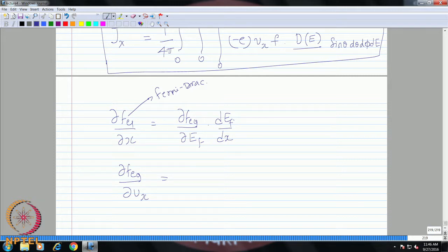Mu is your Fermi level, you can say that is your electrochemical potential mu. At 0 Kelvin, that is your Fermi level. Okay. So, that is a function of x when you have a charge gradient. Now, what I am asking is, what is the gradient in the velocity space, momentum space, through which variable is it a function? Definitely not EF. So, what are the other remaining variables? Temperature, definitely not.